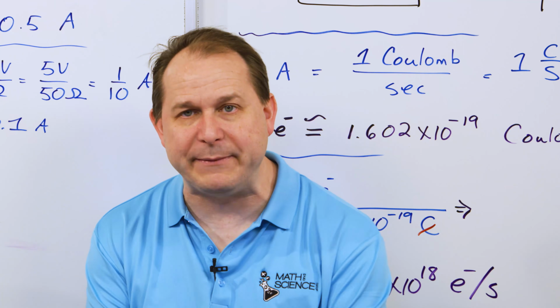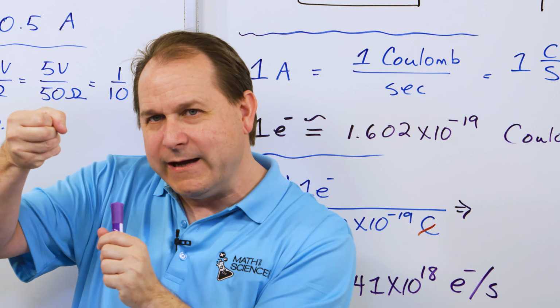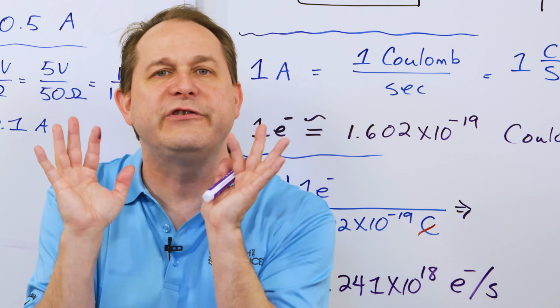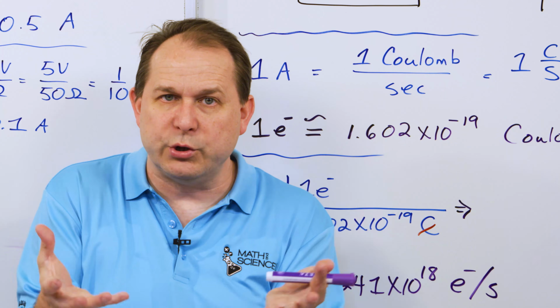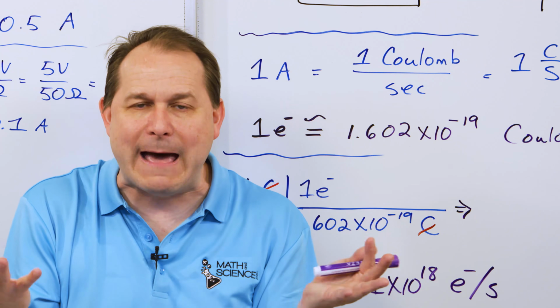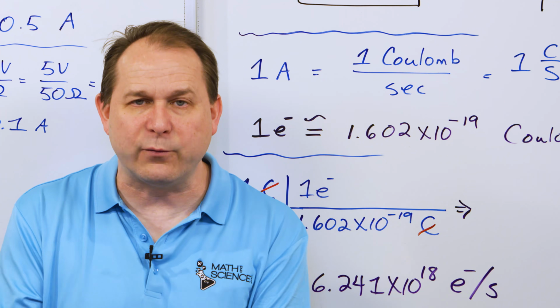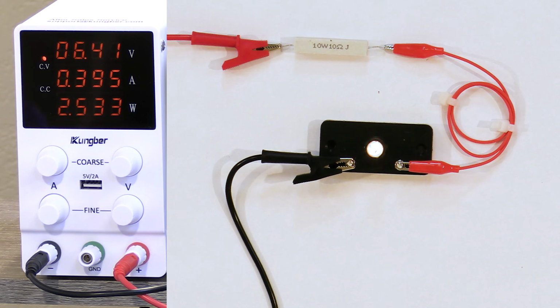There is still pushing happening across the terminals of the circuit, just like there can be pressure in a garden hose. But if the spigot is closed, or I let go of the handle and no water can flow, there's still pressure in the hose. You can think of pressure in a balloon or something. You blow up a balloon, there's pressure in that balloon, but there's no flow coming out of the balloon. So nothing's going to happen, but I can still have pressure, I can still have voltage with no current flow. That's why there can be voltage here, but no current. As soon as I connect the circuit there, then the push begins to be able to push, the voltage can push the charges around the circuit, and so the thing begins to operate.